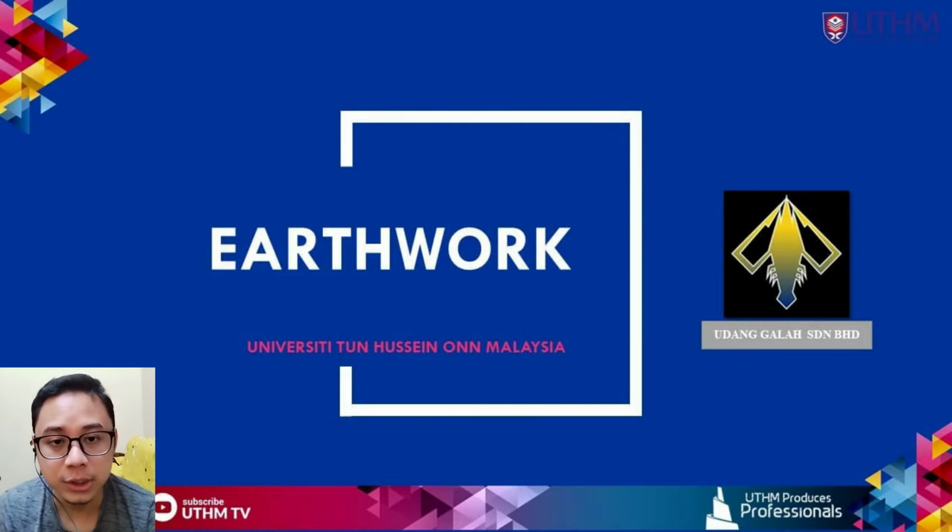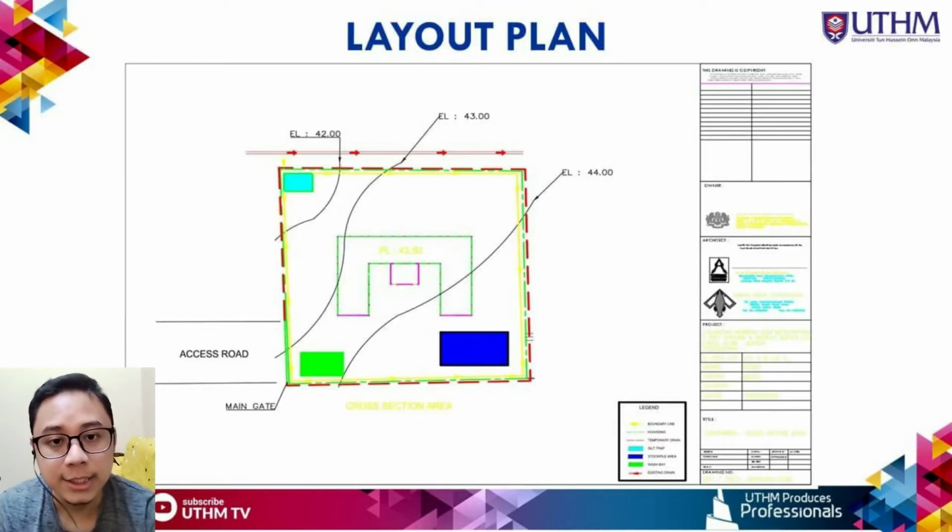The first part of the infrastructure work is the earthwork, and this is the layout plan of the earthwork. There is the contour line, the existing level. The existing levels are 42, 43 and 44. The proposed level that needs to be done at the site area is 43.50. In this layout plan of the earthwork there is also the hoarding area, the stockpile area, the silt trap area, the drainage area and the wash bay area. This layout plan also has the entrance of the site area and the access road to enter the site area.